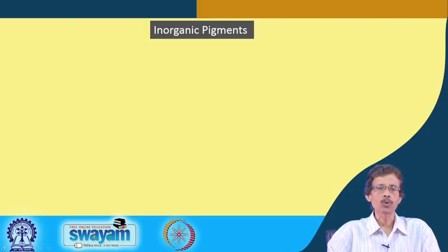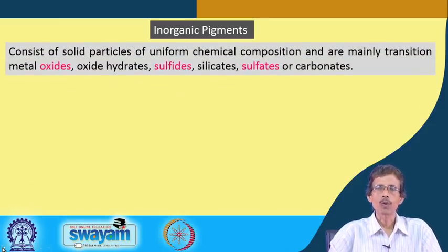But the corresponding inorganic pigments have huge applications, from making inorganic-material-based paints, to the material we can put in ceramics, in enamel, and also in some kinds of polymeric material which can withstand high temperature. These inorganic pigments are very stable, even at very high temperature, so their degrading behavior with time and with weather, the moist weather and all these things, would be very little. So, they do not degrade quite easily.